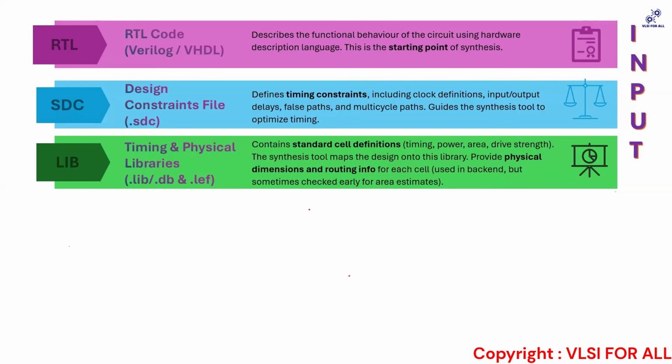then instead of another masala that is less strong, say Catch masala is not that strong, you select from the pantry the ingredients that make your dish as per your requirement. The same goes in this industry. In the library there can be different variants of various gates. Let's just take a simple AND gate, a basic gate. For example, there can be an AND gate of different drive strengths. As you go higher in drive strength, your device will be much faster, but since you're increasing the drive strength, you're increasing the area of your cell.